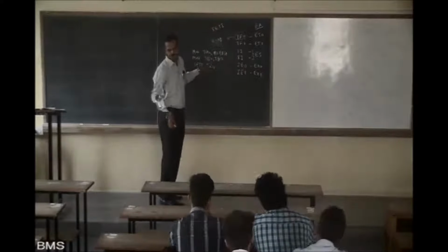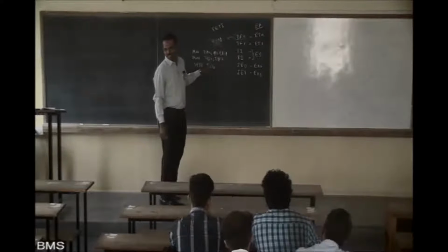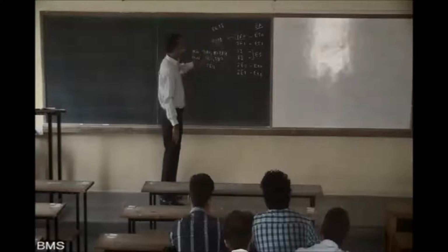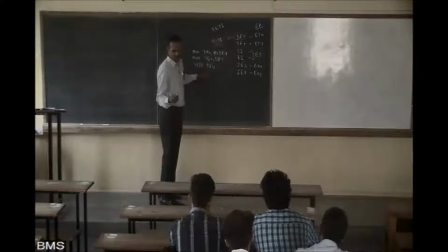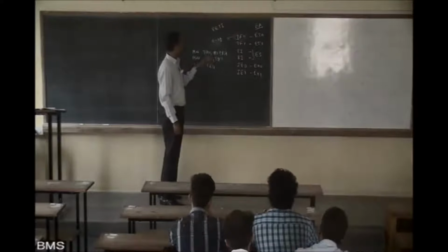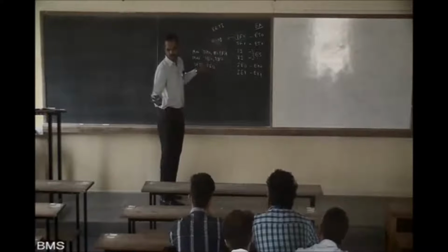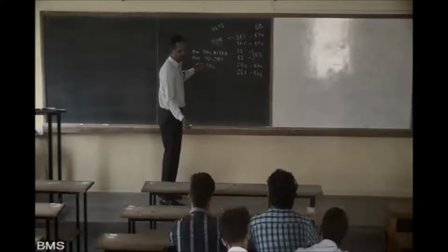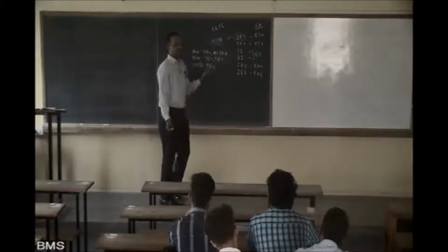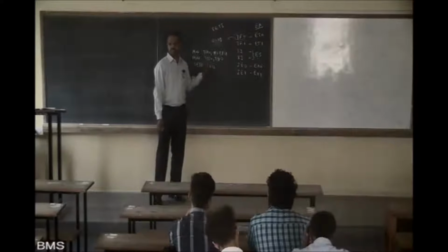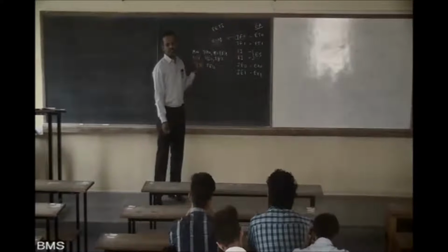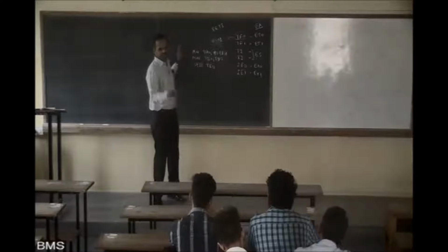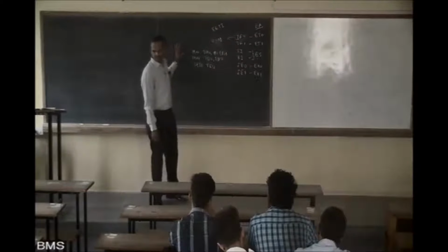It is not required, but if you write it, there is nothing wrong. You are understanding the point? In mode 2, you need to put a value only to TH0. When you set bit TR0, the first time, this gets copied to TL0 by itself. There is no need to do this explicitly, but if you do it also, there is nothing wrong. Is it clear? Yesterday we had this point. Done.